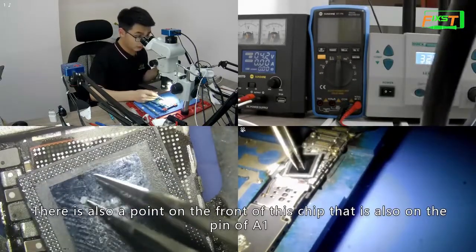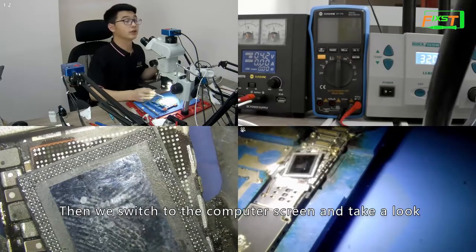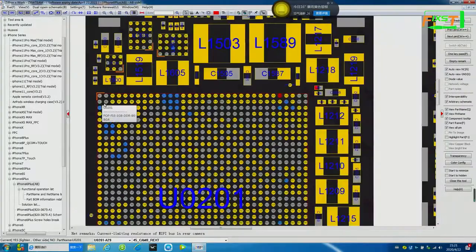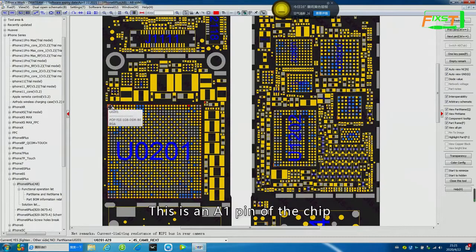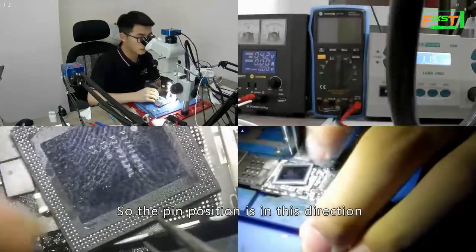There is also a point on the front of this chip that is also on the pin of A1. Then we switch to the computer screen and take a look. There is an arrow when the mouse moves here. This is the A1 pin of the chip. They correspond. So the pin position is in this direction.